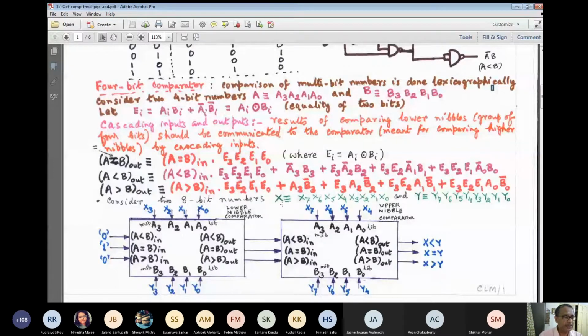If we want to find when this becomes equal, then I have to look only at whether this is 1 or 0 and at the bitwise comparison of A0, B0, A1, B1, A2, B2 and A3, B3. So when specifying the middle one, A equals B, it matters only whether this is 1 and, in addition, whether the comparison of A0 and B0 gives 1.